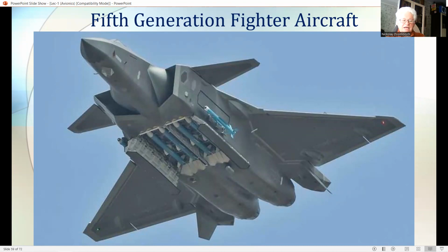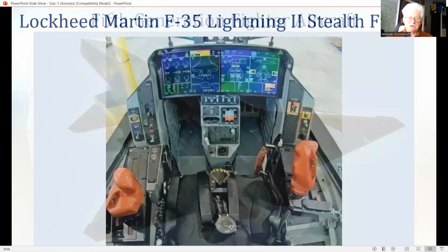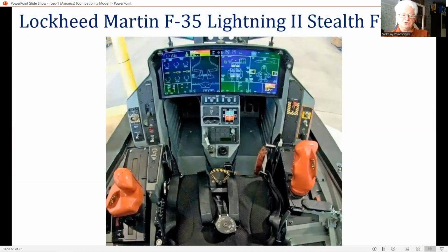The aircraft is a high-agility single-seat fighter strike aircraft with an outstanding performance. The foreplane and ailerons provide positive trim lift, as it is highly unstable in pitch at subsonic speed. Time to double pitch amplitude following a disturbance is around 4.1 seconds. It is also unstable in yaw at supersonic speed because of the reduced fin size.